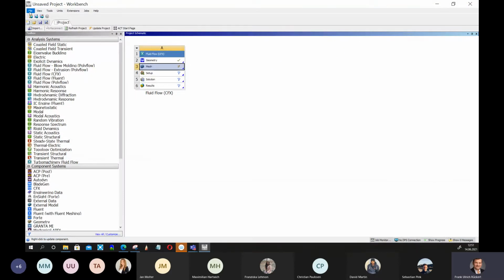Yeah, please, before we save it, that's always a problem with the Ansys Workbench. Your mesh is already finished, but the small flash does not change to the green tick. I do not know why this happens. I think it's a little bug. So you always have to go again on update, and you have to update it by hand.